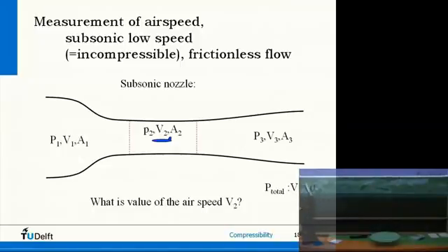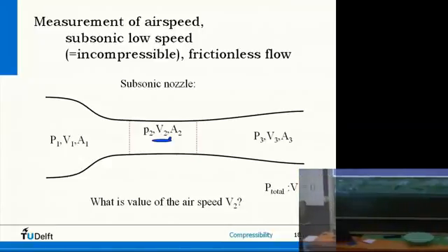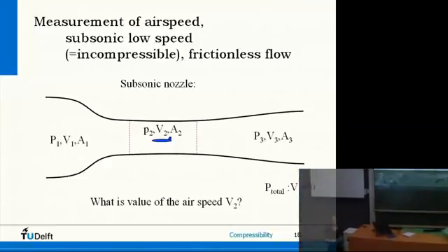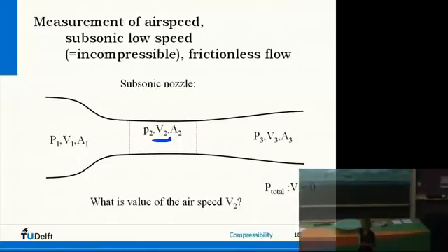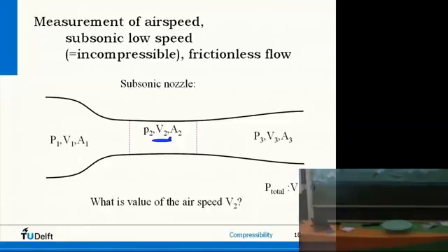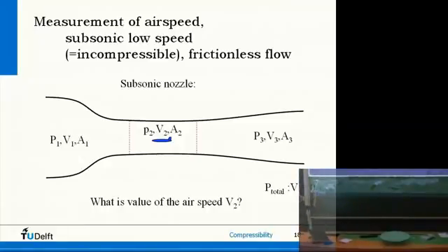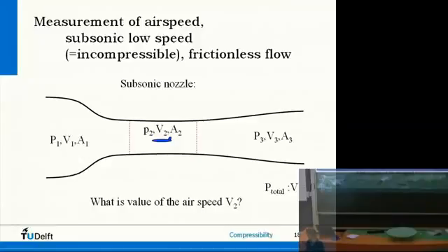Speeds. Of course, the notation is a bit confusing. I introduced speed as a vector with a direction, right? Here, I always do a one-dimensional balance. So my velocities here have just one direction, typically horizontally. I don't assume changes throughout my cross-section. I have a cross-section, and I assume unidirectional, uniform flow, so viscous effects are not important, and that is my speed. So it is not really a vector because I use scalars on the other side. It's only the x direction.